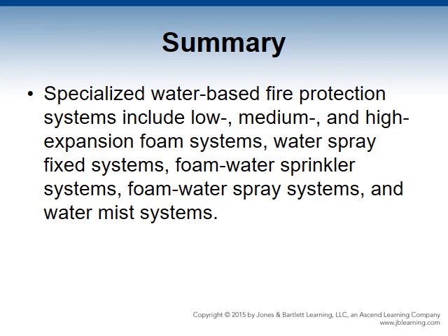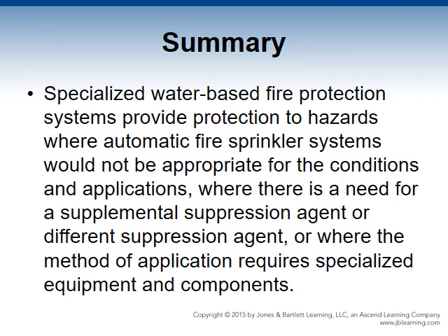So in summary, specialized water-based fire protection systems include your low, medium, and high expansion foam systems, water spray fixed systems, foam water sprinkler systems, foam water spray systems, and water mist systems. Specialized water-based fire protection systems provide protection to hazards where automatic fire sprinkler systems would not be appropriate for the condition and application, where there is a need for a supplemental or different suppression agent, or where the method of application requires specialized equipment and components.